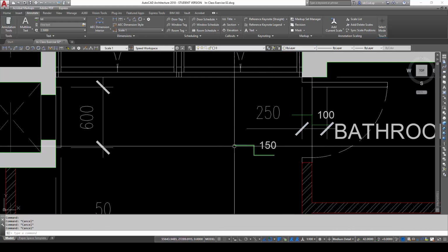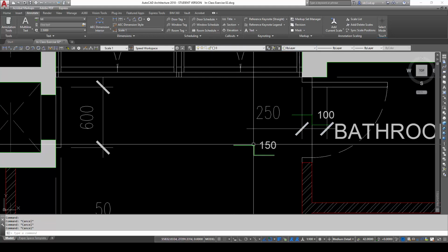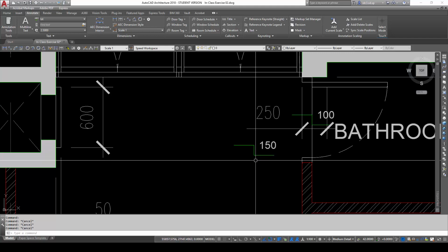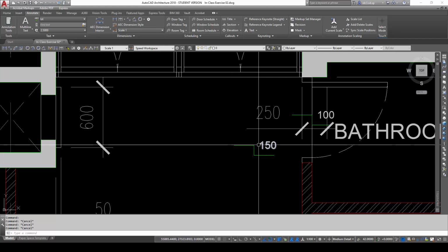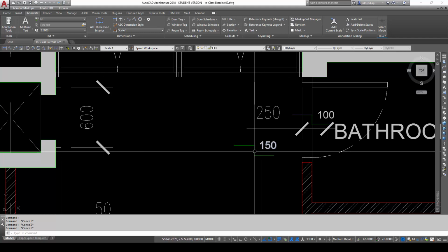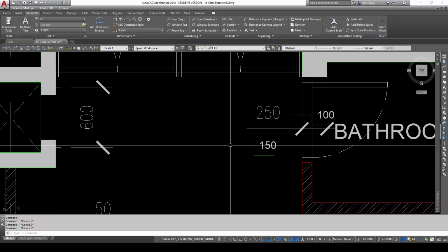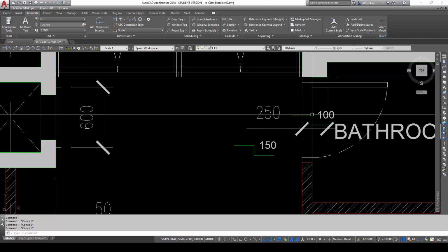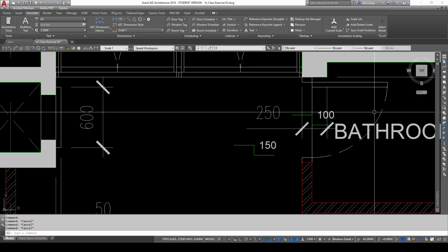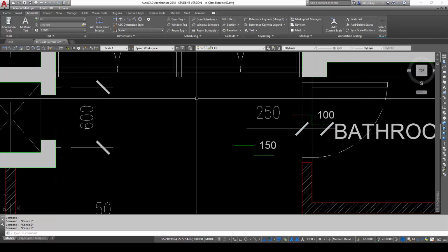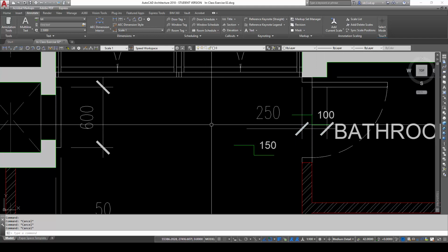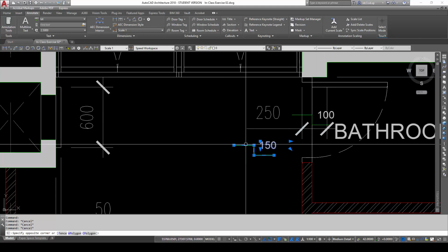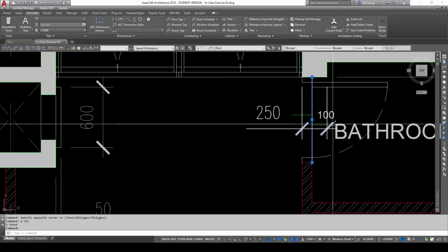This is because we wanted this drop line to be obvious and thick. We almost read this drop symbol like a section. So the one with the number will be the lower portion here. It's a sectional drop. So this would dictate this is lower by 100, whereas the floor level here will be higher by 100. Okay, so that's how it's being read.